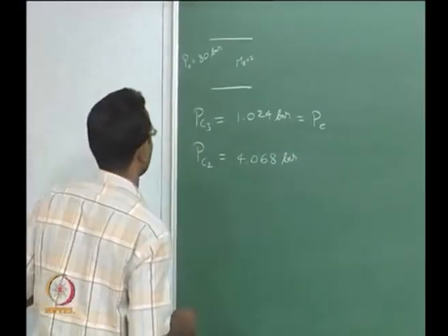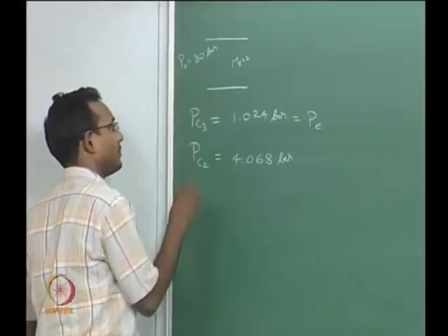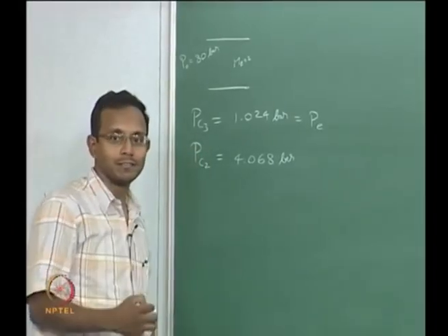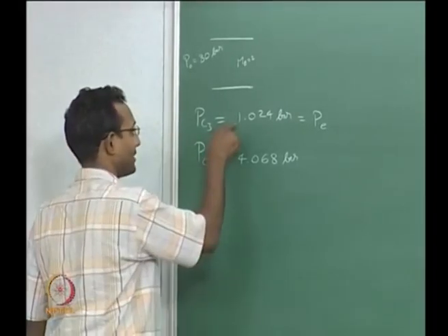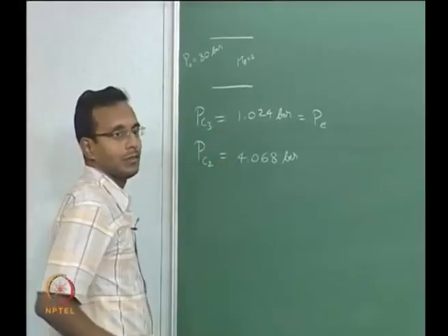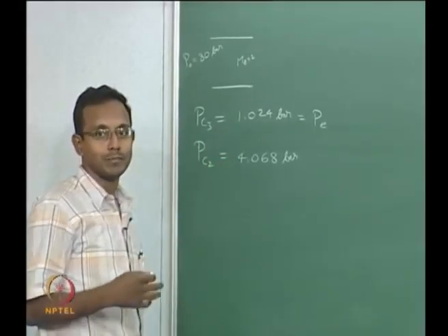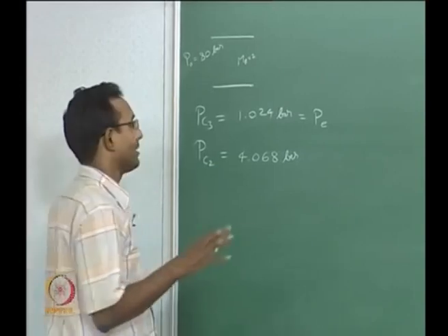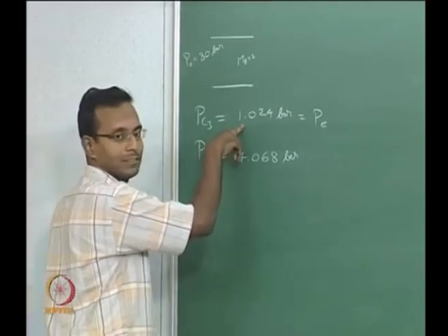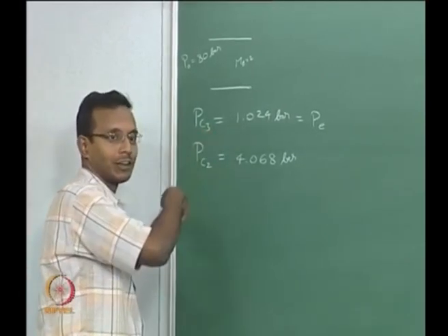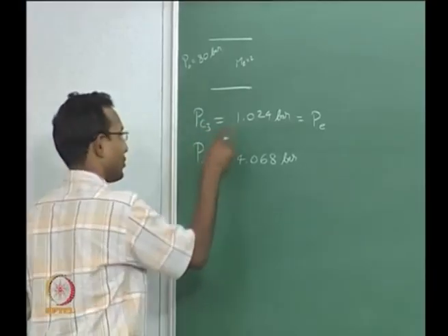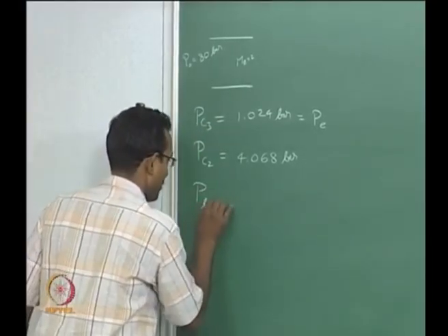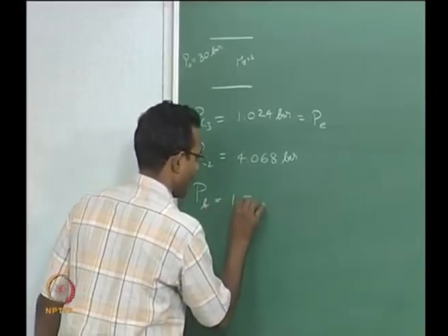And so we wanted to pick a case where there will be an over expanded jet. So we said the value should be something in between these two. To not have problems with Mach reflections at the center axis, we picked a case closer to this end so that our shocks will be just clean crossing like an X. So I picked a back pressure of 1.5 bar.